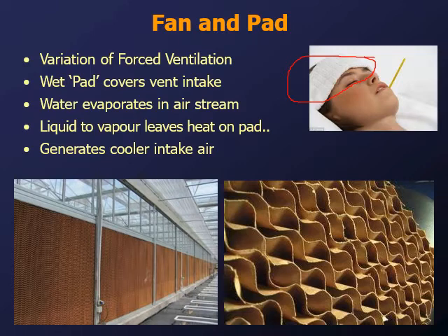So water evaporates in the airstream, and that liquid to vapor transition. When water goes from liquid to vapor, there's an interesting thing called enthalpy, where in order for water to turn from a liquid to a vapor, it has to absorb energy from the surface that the liquid was on. So when water evaporates off this cardboard, it physically cools the cardboard, and subsequent air that comes through is cooled by that cooler cardboard.